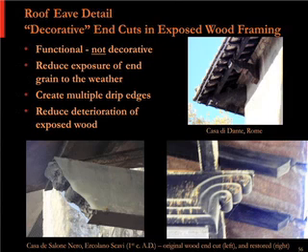And then when you get into the medieval period, a lot of times the mortar isn't as durable. They weren't using that much pozzolana. They kind of built with what they had. But probably as a result of that, you do see very, very huge roof overhangs on medieval buildings, and that's what you're looking at the top right. So the masonry wasn't as well built, but huge roof overhangs help to compensate for that.